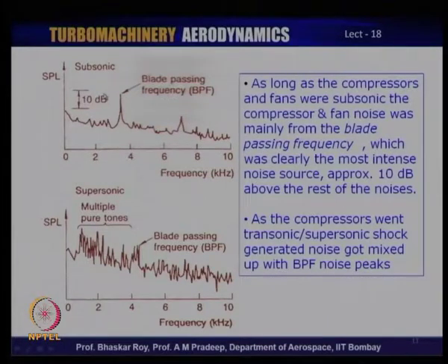And in an old fashioned subsonic compressor, that blade passing frequency was the most identifiable noise source or tone, which is easily at least 10 dB above the rest of the noises, as it used to be.